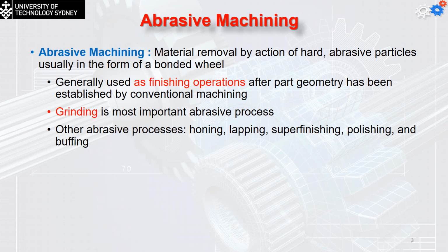And this will have very high accuracy due to the cutting process. So we said we had to remove the material in chip form. That means we have to go for a depth of something between 0.1 millimeter up to, let's say, 4 millimeter in most of the cases.